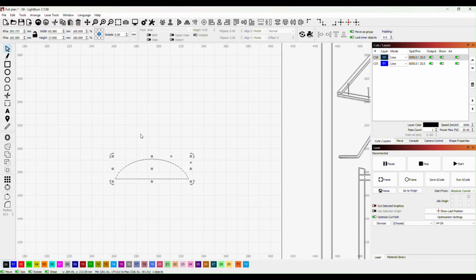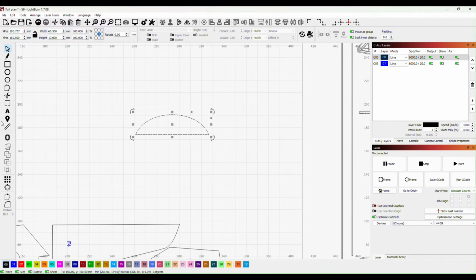So the way to position these is, if we create a shape there which is 3.2mm wide, so we've created our rectangle, and then we come up here and we go 3.2, and then we'll do the same for the height, 3.2, and what we've got now is a little square that can fit on the top here, and we'll be able to use that to make the correct size of slot in our former. So I'll just bring that down, I'll put it there.